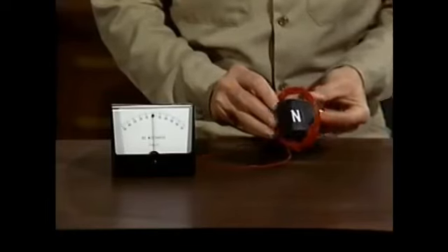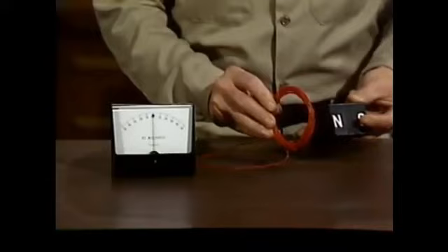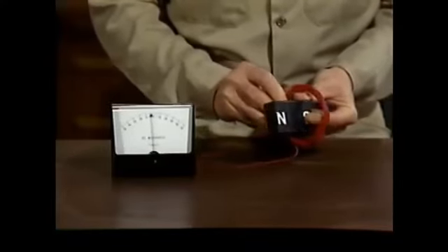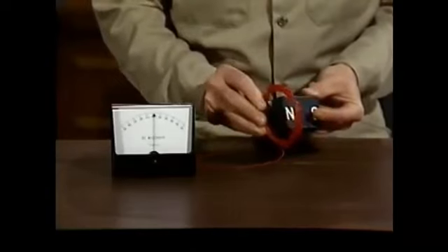The same thing will happen if the magnet is held stationary and the coil is moved around it. That's what relative motion means. Either the conductor or the magnetic field has to move. The electrical potential that's created in this situation is usually referred to as an induced electrical potential. The conductor, the magnetic field, and the relative motion induce an electrical potential in the conductor. This is the basic principle behind the generation of electricity that's used to operate equipment in industrial facilities.